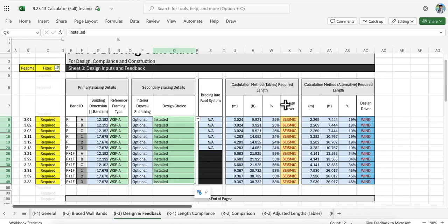It's a requirement of building code that we review our design for lateral brace requirements for wind, and then for seismic activity, and then we take the most restrictive of those two options. All this is identifying is which of those options is actually being picked based on the method you're using to calculate it.